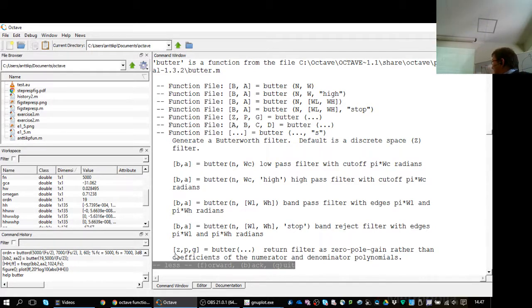Okay, and the same thing here, that you still need to find out the order number from the transition bandwidth and attenuation requirement. So basically, come to think of it, the whole box needs only that corner and that corner. So you have a pair of the stop band start frequency and attenuation factor. And then you have this cutoff frequency and where that is defined at the ripple level.